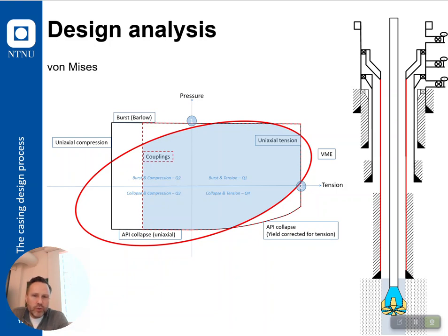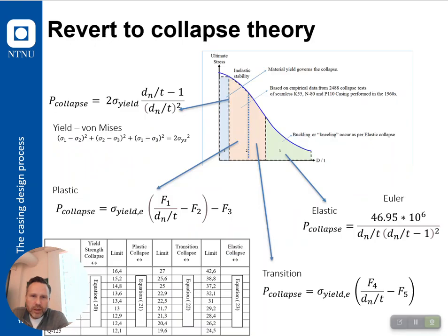Now would be a good time to show you that calculation. Basically, it's a pre-calculation for all of these calculations except for the elastic. What it does, it takes your yield strength and gives you a reduced yield strength based upon the actual stress.